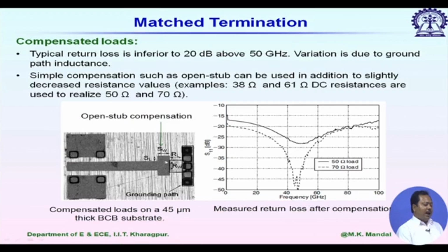Usually the fab lab will give you a standard thickness for that nickel chromium and a standard resistance per centimeter. Then you have to choose a proper dimension. So, you know that resistance depends on length and width. Accordingly you have to select your length and width to realize a given resistance value.